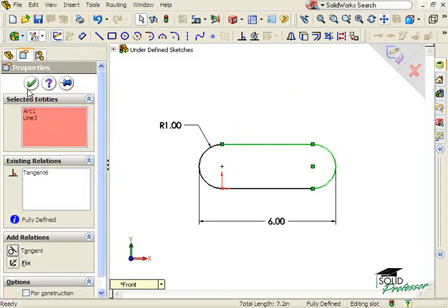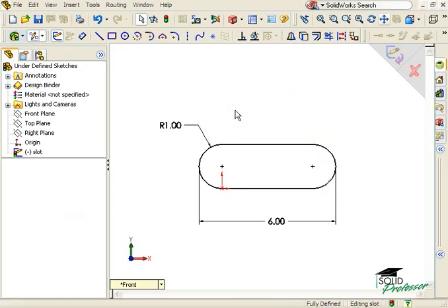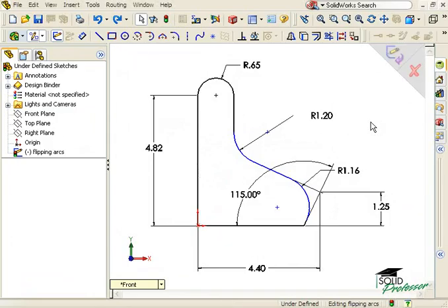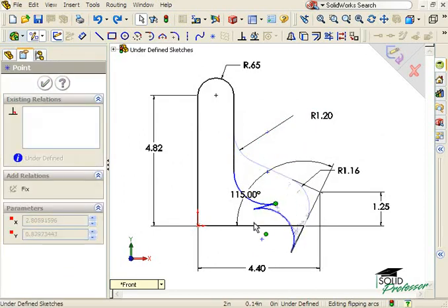As simple as this technique is, many users, and particularly new users, are reluctant to use it. And I'm not sure exactly why, but one possible explanation I've seen is the fear of breaking the sketch entirely. See, sketches like this one that include arcs tend to make users especially nervous. This is because when you drag entities, arcs can start flipping due to changing geometric conditions.